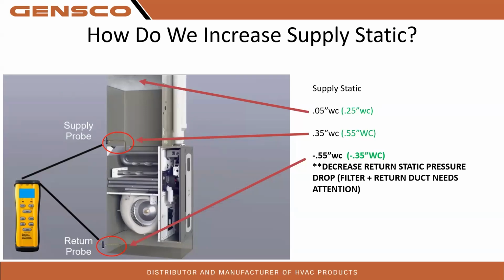You think about a mobile home. The supply ducting on a mobile home is so bad, there is no return. The return is the louvered door that goes by the cat's litter box next to the laundry room, right? I mean, that's the return duct. And the supply static is so terrible and so restrictive that we don't have room for supply or return duct. So when you talk about mobile home rated, keep in mind what goes into that.